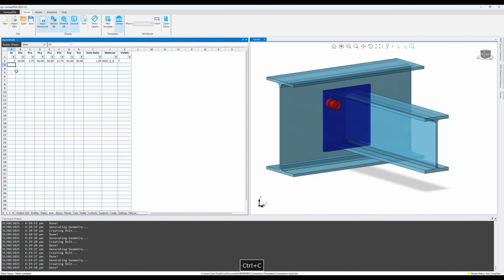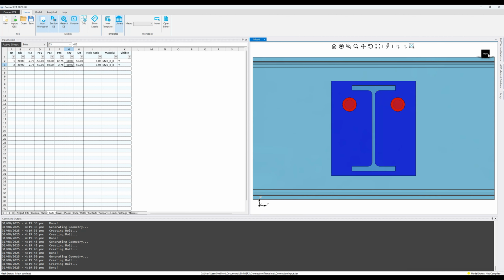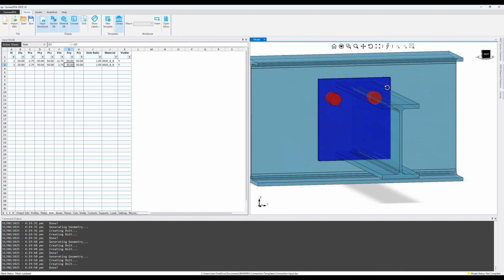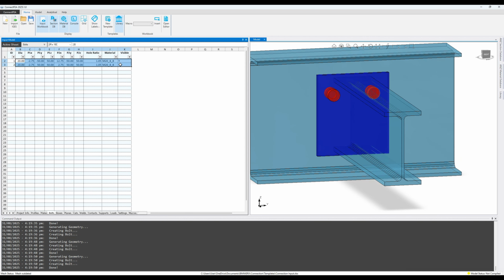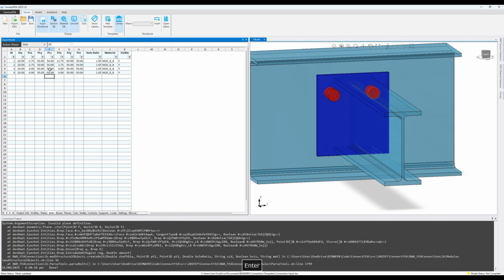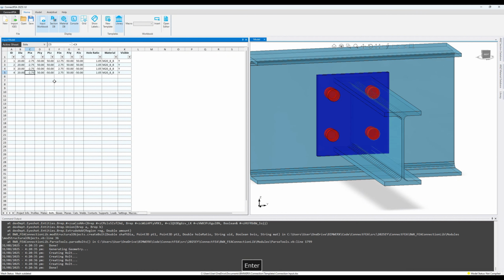And for the other side, we said, let's make it half the width of the web plus the thickness of the plate, meaning if we change the thickness of the plate or the member profile for that main member and the web thickness adjusts, then our components are going to be dynamically adjusted as well. And then I'll just copy that bolt across and use some of those properties to create my top row and my bottom row and complete the rest of my bolts.